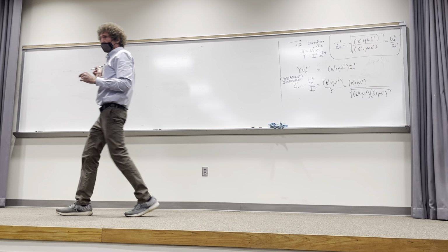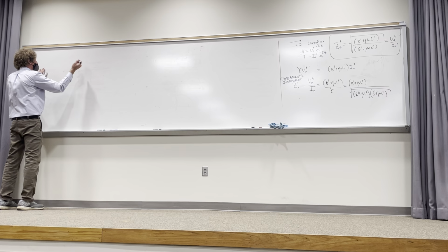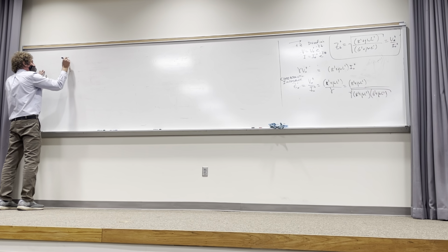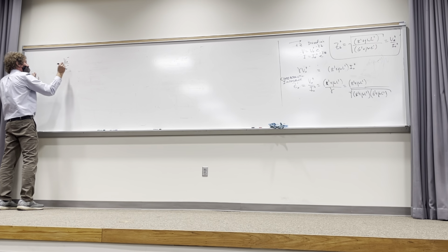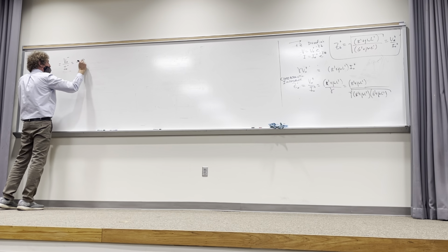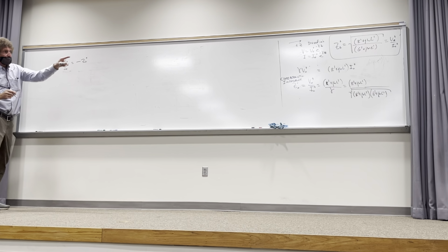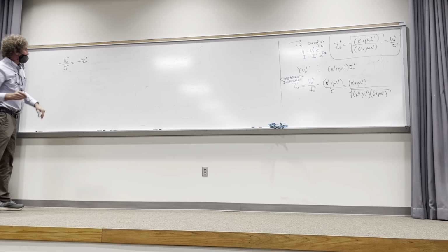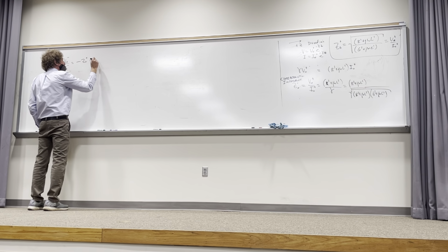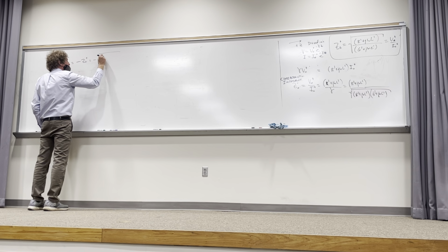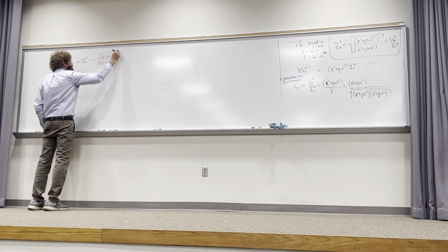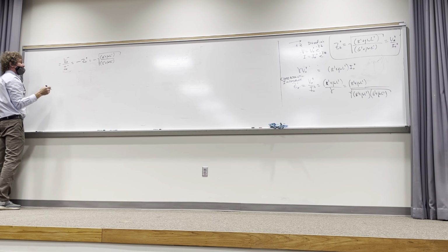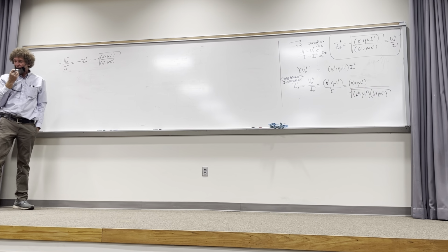However, if you were to do the same process for the negative going waves, you would get the ratio of V0 minus to I0 minus equal to minus Z0 plus. All right, so it'd be equal to minus that right there. Or it would be minus the square root of R prime plus j omega L prime over G prime plus j omega C prime. And that's important. You'll see why in a bit.